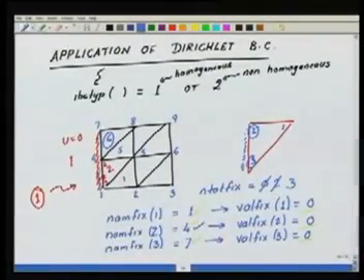But one thing I would like to point out again is that, remember, we are applying the boundary conditions on the edge and not only at the nodes. There is always a misconception that the Dirichlet conditions have to be applied at the nodes and that the force conditions have to be also applied at the node. We are doing integrals along lines, along edges. Those integrals actually translate to fixing of values or assigning of loads to the degrees of freedom sitting on the particular edge. This is something that we have to always keep in mind. Okay. So now we should be able to solve the problem.